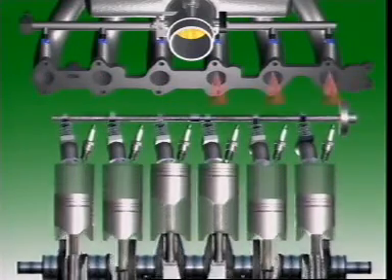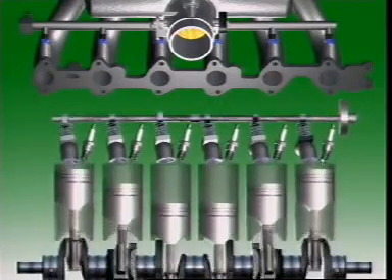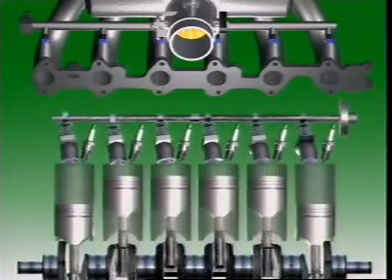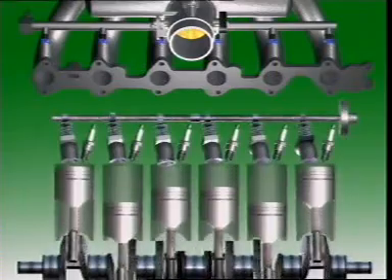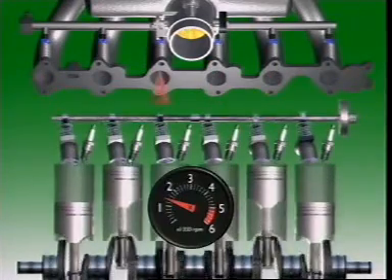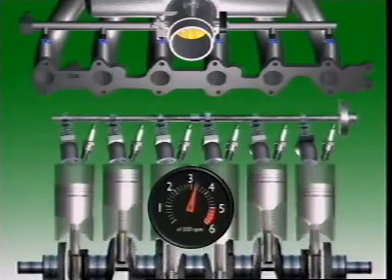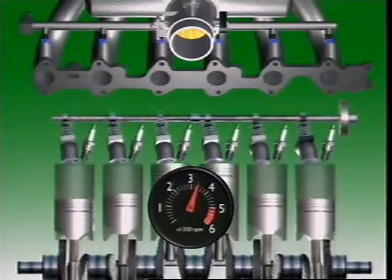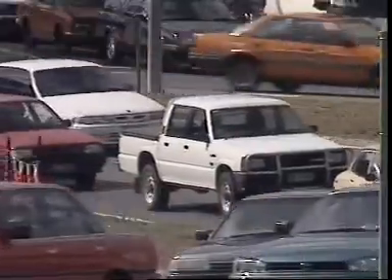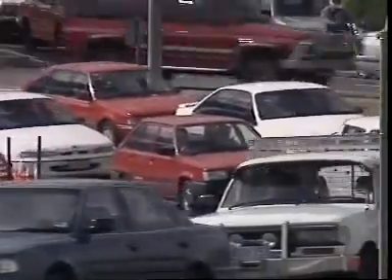In some applications, different modes of injection are combined so that the mode changes according to the operating conditions. Sequential mode may be used for low engine speeds, changing to simultaneous mode at high speeds. The same principle is used in changing from light loads to heavy loads.